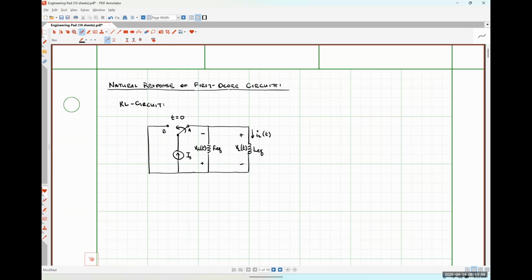A short circuit, okay? So how much current is flowing through that inductor? All of it, so all of I of S. So essentially, we have some amount of energy that is being stored by that inductor LEQ, okay? Because there's a current flowing through it, there's energy stored. We know that the energy stored in an inductor is 1/2 Li squared, right?